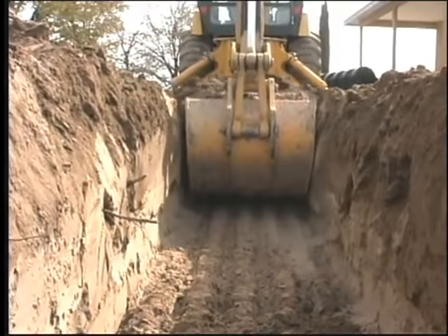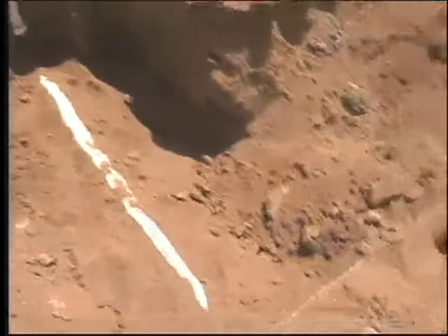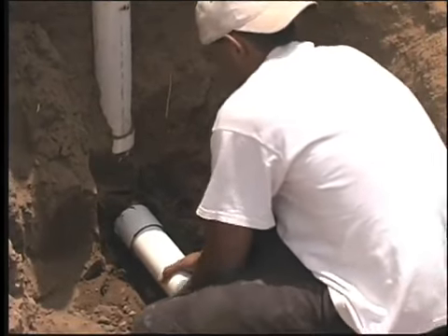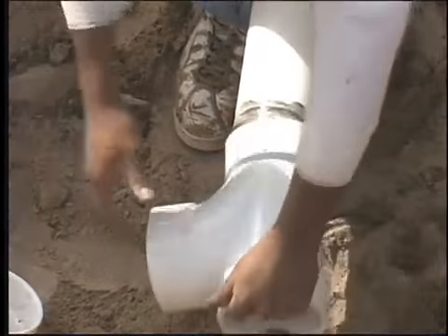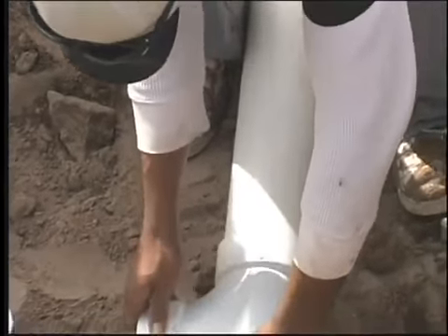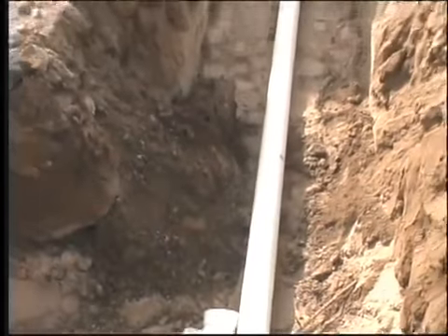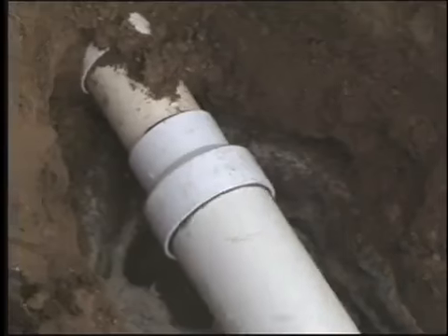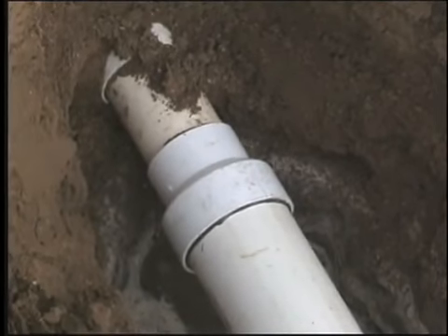Now that the trench is dug, install the drain pipe. 4-inch minimum diameter sewer pipe with watertight connections should be used between the house and the septic tank. The possible exception to this is mobile homes in place where local code allows 3-inch diameter sewer pipe. The sewer pipe can go all the way to the septic tank. There are very few septic tanks with a 3-inch inlet, so it will be necessary to use an adapter to adjust the 3-inch pipe up to a 4-inch pipe.